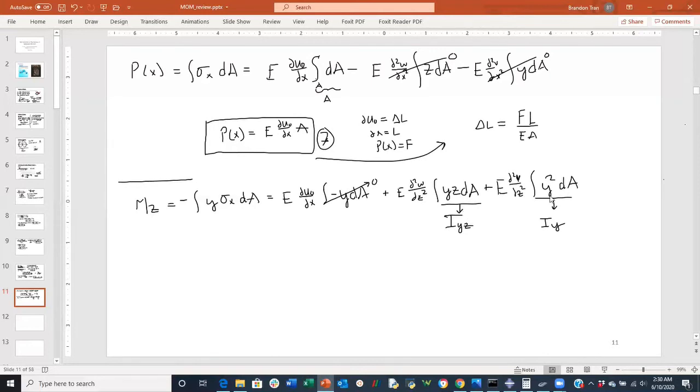So for example, if you did the integral for a rectangular cross section, you will get your traditional b times h cubed over 12. So you'll yield the same equation. It's very interesting. We gather the second moment of inertia terms through this derivation. So we've essentially developed the moment about the z-axis equations that relate the curvatures with the material property of the beam to the second moment of inertia, the second moment of area for the beam.